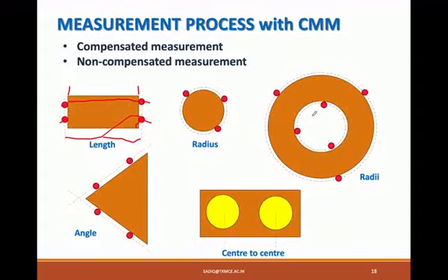That's very interesting. You see here, if this is a tube, on the inner side it's vacuum, there is no material. If the diameter of this cylinder and this cylinder are to be taken, conventionally, as we perform the measurement, we pick many points on the circumference of the cylinder, so that the actual radius can be obtained by reducing the radius of the circle fit by the system.